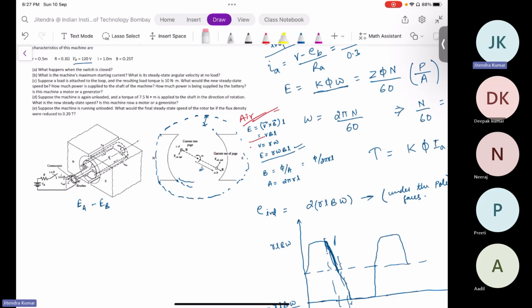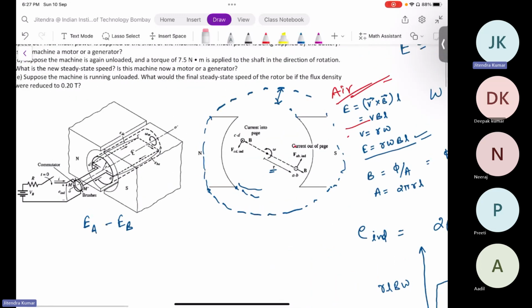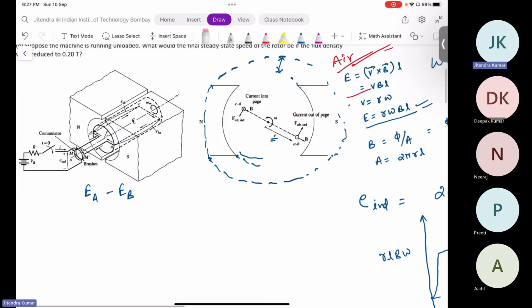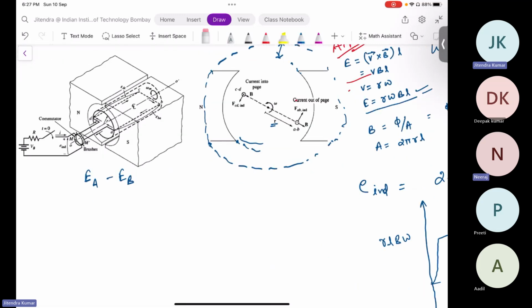And we see, if some company is designing a DC machine, it is designing certain width and length of the core. That is dependent on how much flux is flowing. So you see the saturation level of this silicon steel, it has 1.8 Tesla of limit.